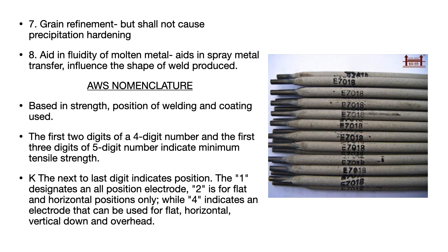And one of the main important functions associated with fluxes is grain refinement. For grain refinement, many types of elements are added, like nickel, boron, vanadium, niobium. This nickel basically is not for grain refinement, it is for austenitic stabilizing, whereas grain refinement is basically done with the help of microelements like boron, vanadium, niobium, etc. But care shall be taken so that precipitation hardening is not happening.